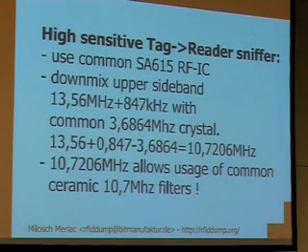What we didn't want is to buy expensive antenna equipment. You can't use the existing electric antennas, you need a magnetic loop antenna. Magnetic loop antennas are awfully expensive, but we found out that's only because of one thing. The point is that the magnetic loop antennas you can buy freely and they're expensive are used for sending also. You need very expensive adjustable capacitors for this kind of antennas because we have very high voltages when sending.